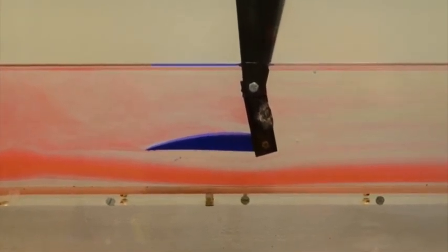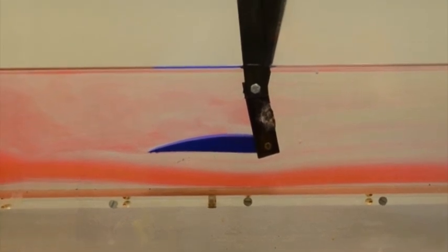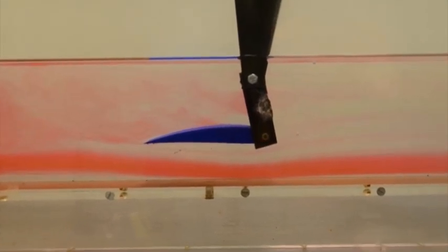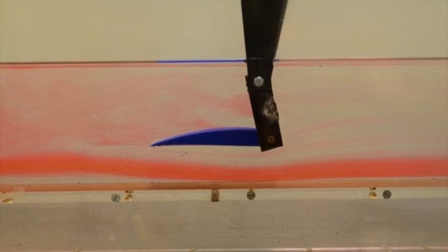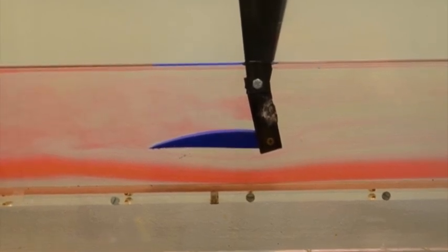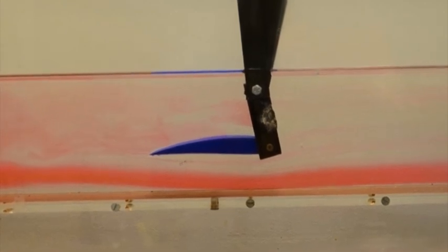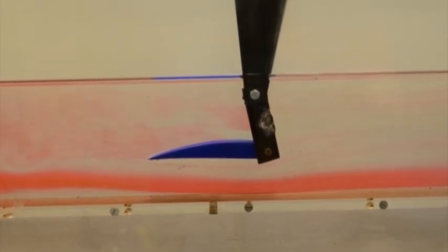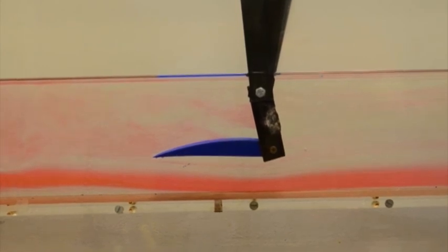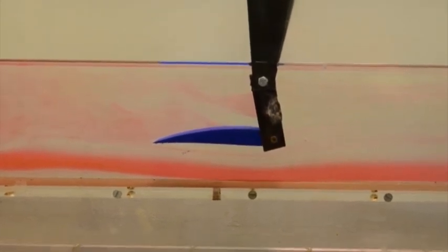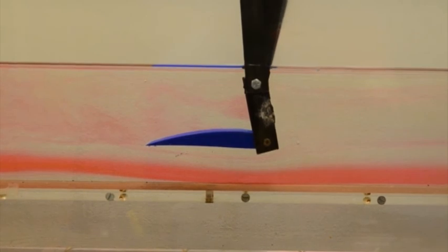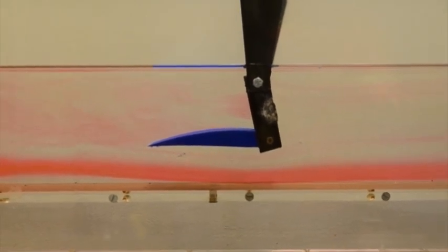Streamlines have many uses, but one of the most important comes when the Bernoulli equation is applied to it. For steady and incompressible flow, the sum of the mechanical energy, potential energy, and kinetic energy along a streamline is constant. Any increase in one form results in a decrease of another. If there is no change in height along a streamline, Bernoulli's equation becomes a balance between static pressure and velocity.